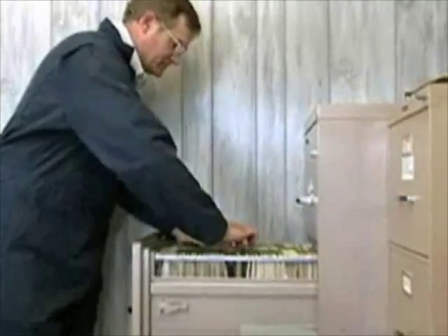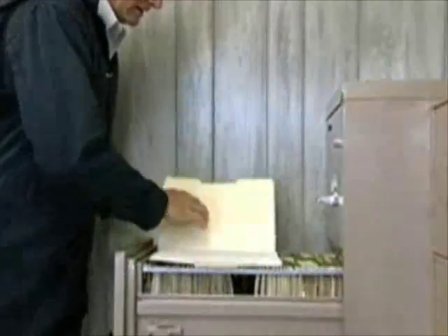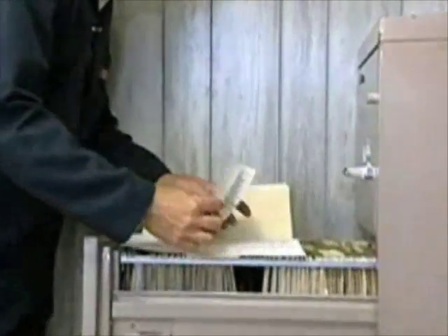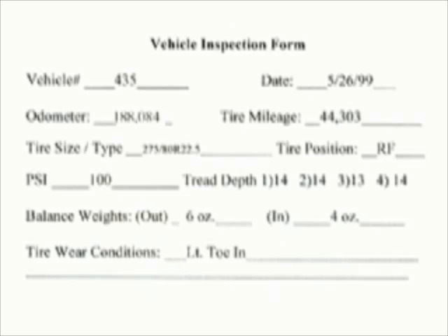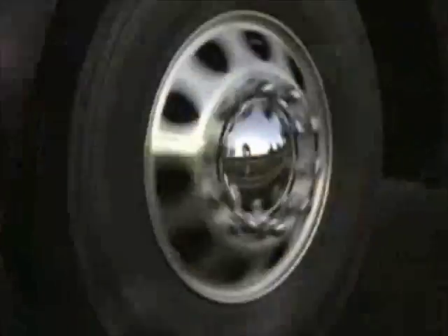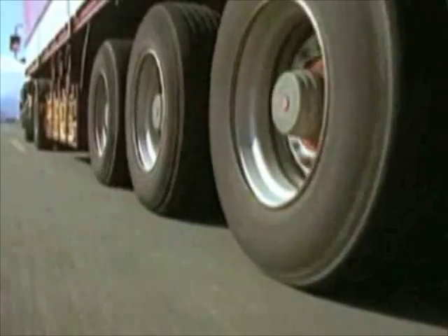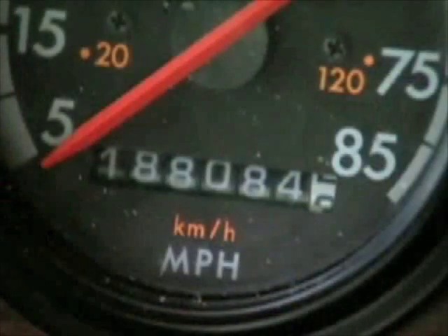Prior to the actual inspection of the vehicle and its tires, it is often helpful to do some basic background information gathering. Try to gather as many facts as you can. Ask questions such as, is the driver available for comments? Is there a vehicle write-up form with information regarding the complaint? Is there a vehicle maintenance file, including alignment facts, parts replaced, damage to the vehicle, etc.? What are the basic tire facts, such as prior tire performance, data on the tires now running, date mounted, and the vehicle's mileage at that time?